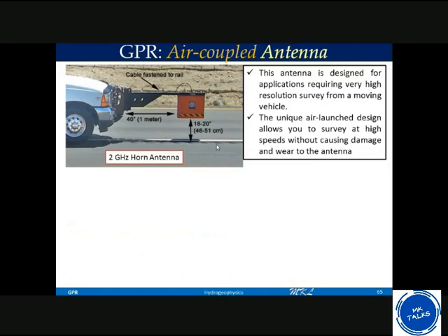Generally, in other countries, they map the whole road with this antenna or GPR technique, and find out how much thickness was asphalt, what the condition was, and how much they have provided. If they have not provided according to the specification, they say, "That's why I won't pay you that much," or they hold the payment until they make it better. So this is a technique to see how good the work has been done.